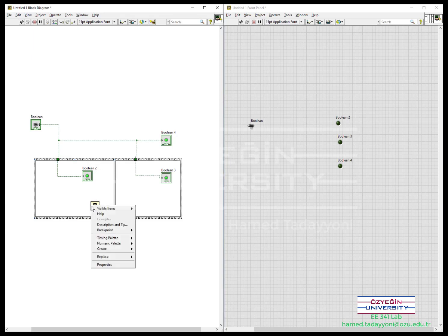So we right click here and we create a constant in order to specify how many milliseconds this should give us waiting. So if for example we need 2 seconds, we type here 2000 because it is in milliseconds, and we just copy this here in order to have the same wait here.